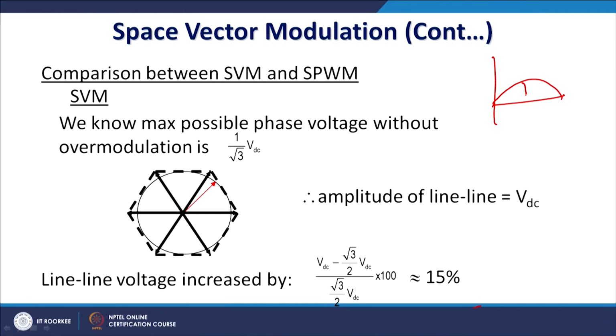One of the problems of PWM is that when you are at 0 you are applying this voltage, but here this duration is shortened. This condition arises only when you are applying the null vector, but in most cases you are switching from one voltage to another voltage, thus you are applying very close voltages, and thus the harmonic content in this SPWM will be much lower than the unipolar PWM.